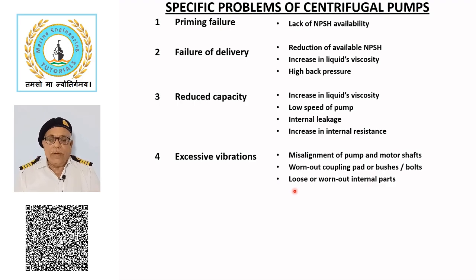Cause of the excessive vibration may be loose or worn out internal parts or rotor touching with casing. Dismantle the pump and check for any loose or worn out parts such as bearings, wear rings, etc. and assemble them correctly. Cause of the excessive vibration may be the pump operation under cavitation. Check pump suction side to rule out any cause for cavitation.